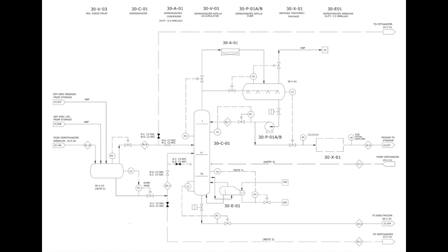On the right you can find the temperature controller, which controls the flow rate of the heating operation done in the boiler. If you look upwards, the upper product goes into a condenser that has a level controller and a pressure controller.